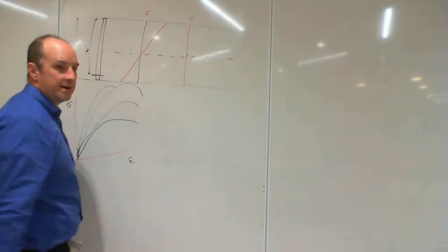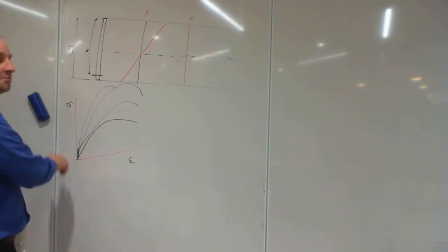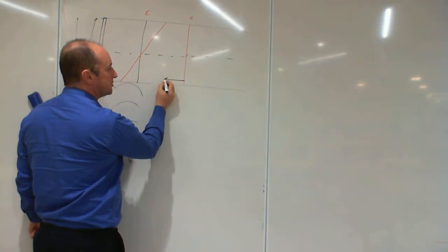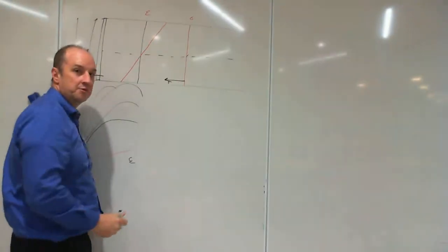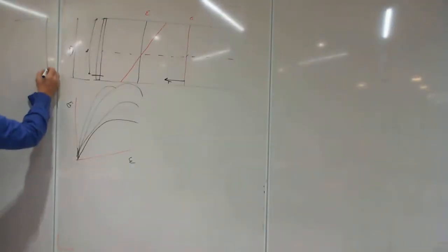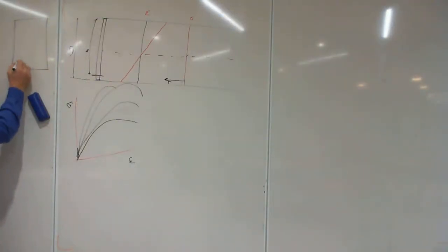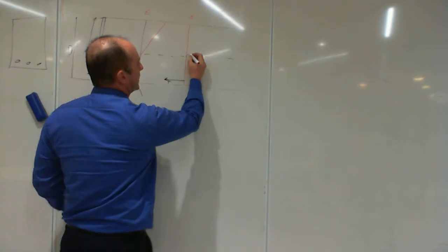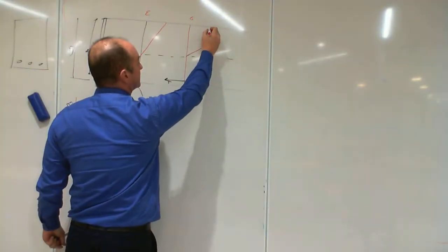Our concrete cracks, assuming zero stress, so we don't get any tension. We only get tension from the steel, and that's all down here. So I put a big arrow there for our tension force for our steel bars. Here's the beam over here, just to remind you. It looks like that. It's got a couple of steel bars in the bottom. And the compression force for the concrete would actually look a little bit like that shape.